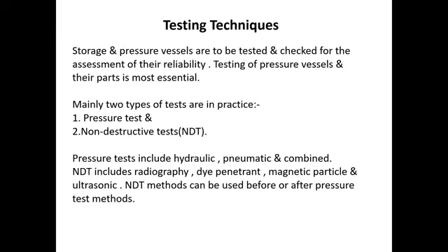So what exactly are the testing techniques used for these pressure vessels? There are two types of testing: the pressure test, and second, NDT, that is non-destructive test. In the pressure test, basically the hydraulic test is preferred by the competent person, and in case the hydraulic test is not feasible, the competent person may go for the pneumatic test or a combination of hydraulic and pneumatic tests.